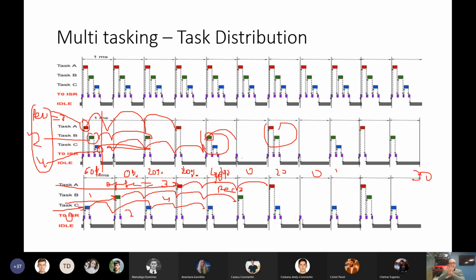And we can see that we can even plan the execution in order to have the lowest possible CPU load, in order not to have an overflow of the system tick. So here we'll have about 20%, 20, 20, 20, 20, 20. Sometimes we have, as in this case, about 20%, never 100% of the CPU load, because we distributed everything in a planned way.